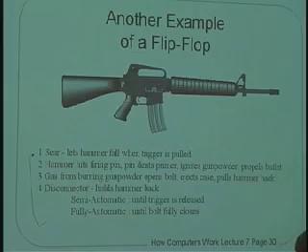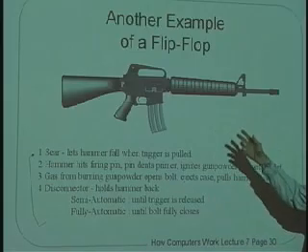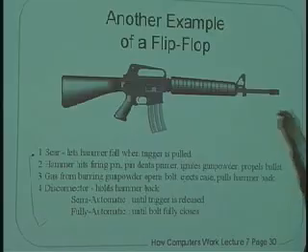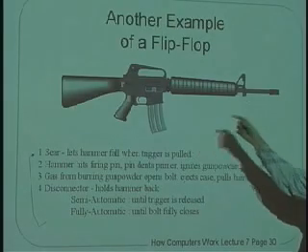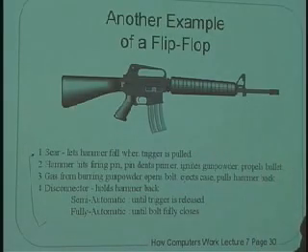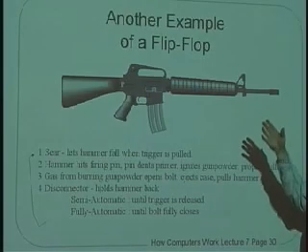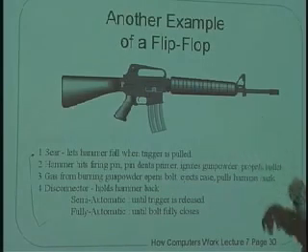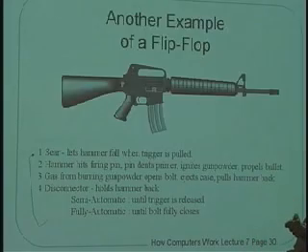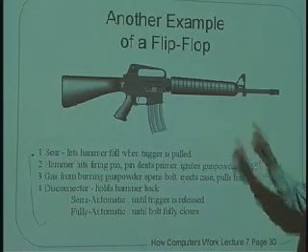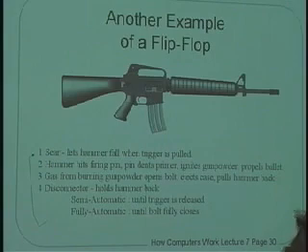You pull the trigger, right, and it goes bang, right? The bullet comes out, and a mechanism goes backwards inside of it, right? And if it weren't for the flip-flop in there, it's in a condition where, because it's a semi-automatic rifle, it has reloaded itself with the next round, and the trigger is still down. All this reloading of the next round happens so fast that your finger, if you're firing one of these things, has not yet lifted off of the trigger.